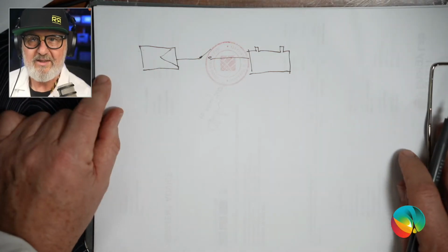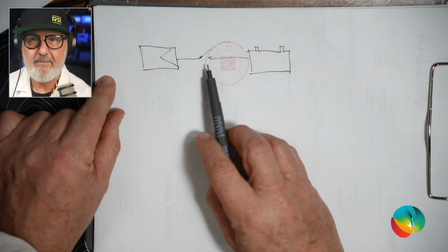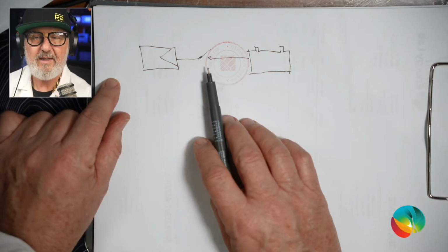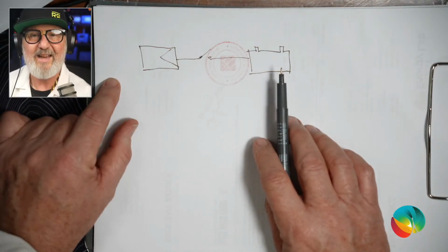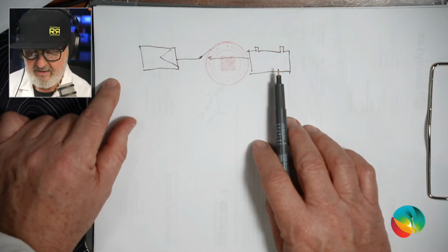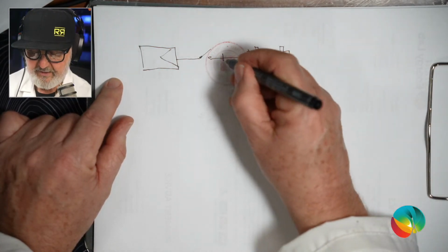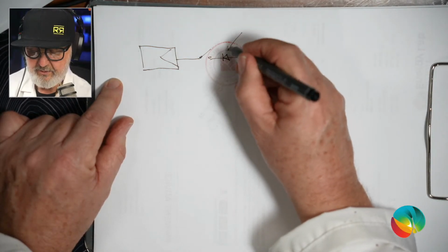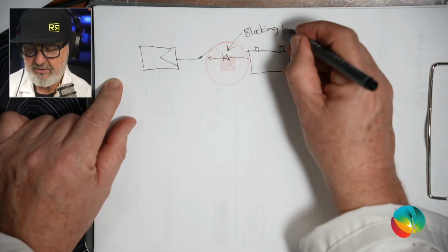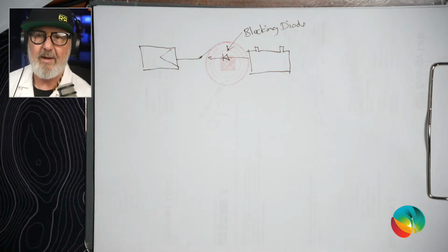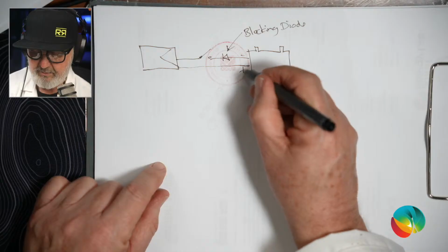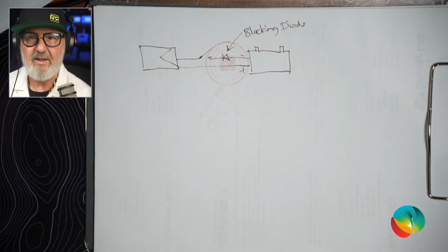Now, the problem with that is, if you don't turn off the solar, you could overcharge the battery. That's problem number one. Problem number two is if you leave a solar panel directly connected to a battery, at night time it becomes a load and it slowly leaks away some of the power that you put into the battery. So some clever person came up with the idea of actually putting in a blocking diode. So what we've got here is a blocking diode. And so it only allows charge current towards the battery. Sorry, of course there's two wires, and so we'll call that the negative, that's the positive. There we go. You can put the blocking diode on either, it didn't matter.